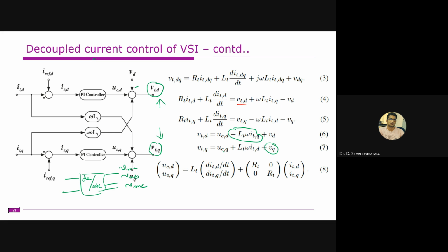So what we are doing is, we are measuring the grid voltages in the ABC reference frame. We transfer them into the DQ reference frame, do all the calculations, and obtain the inverter expected voltages, again in the DQ reference frame. We transfer them into the ABC reference frame, and these are the modulating signals we obtained. From this we can implement the PWM technique.